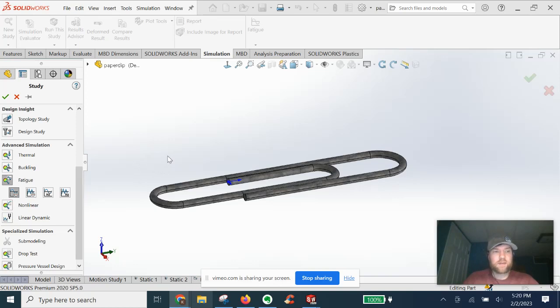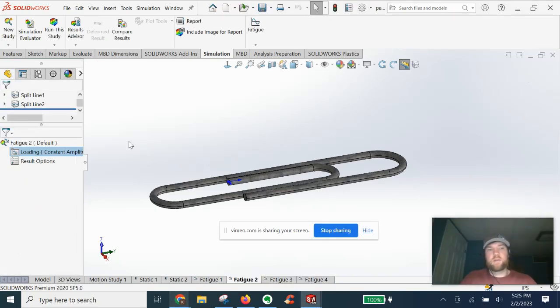It's the constant amplitude throughout, and there's a predefined, fully defined amount of cycles or occurrences of that stress. So whether it's alternating or just single load based in one direction, you're going to have the same mean stress throughout the entire amount of cycles.